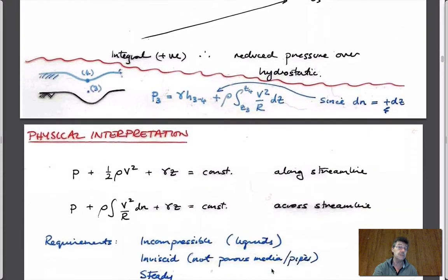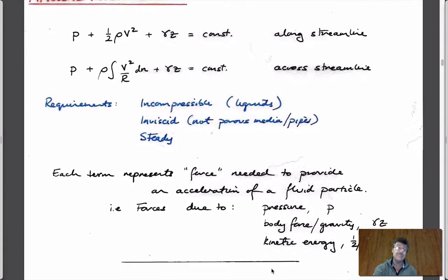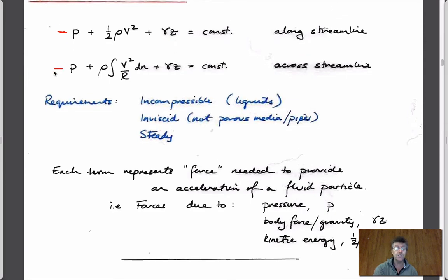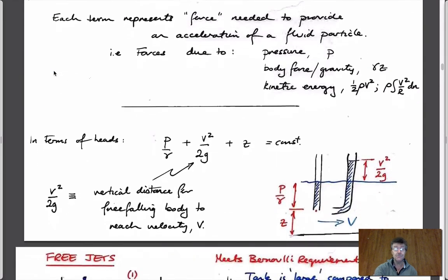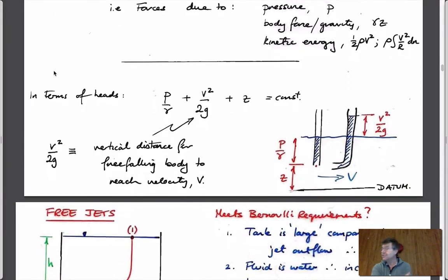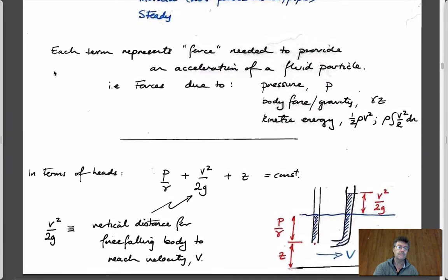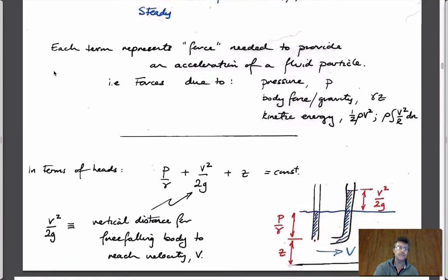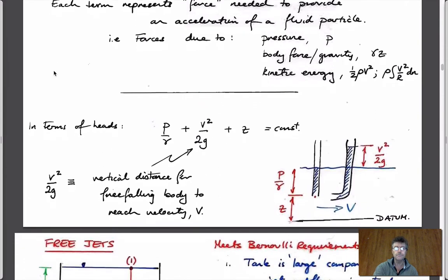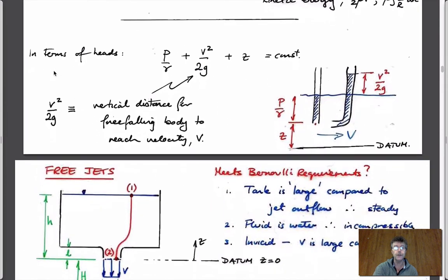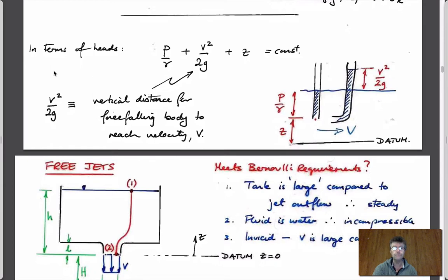All right, so along the streamline, we have Bernoulli's in two orthogonal directions. We've just gone through the one with curvature. You've played around with these examples. Did you do some examples where you had to take the variation across? You're given a distribution, and you would integrate it with changing r, and it would end up having to be like ln. Yeah, fine. So assume it's constant, but maybe you don't have to do that either.